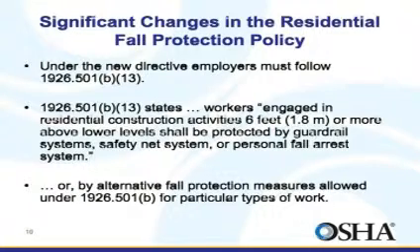Slide guards or safety monitors were allowed in lieu of conventional fall protection without first demonstrating infeasibility or the creation of a greater hazard. The new directive has not outlawed the use of slide guards or safety monitors. Now employers must first demonstrate that it is infeasible to comply with the provisions of the standard or that it creates a greater hazard.